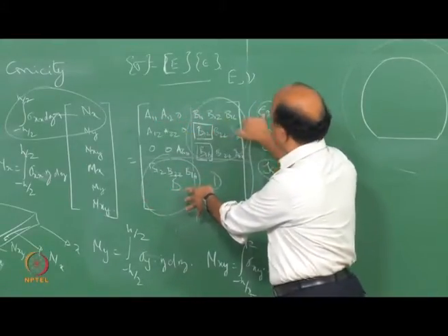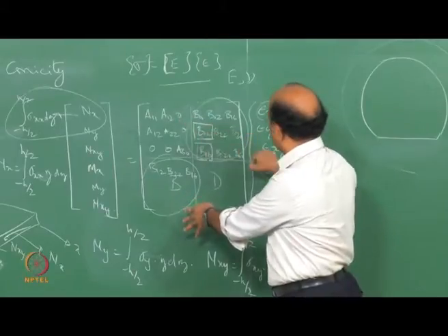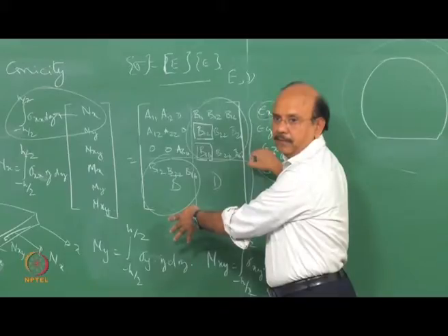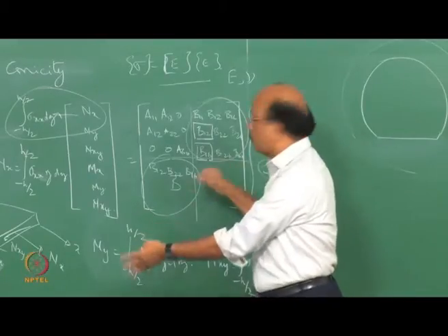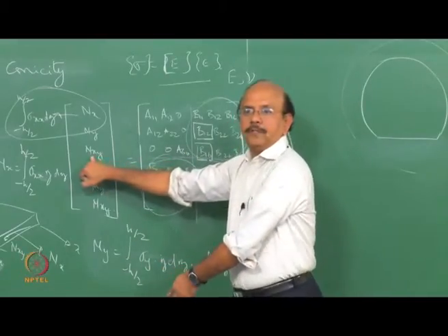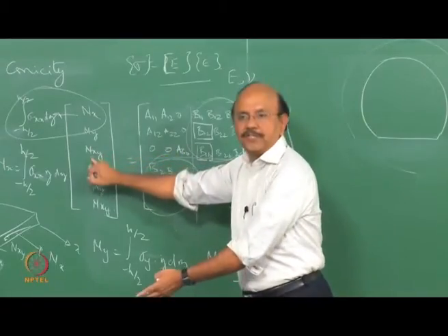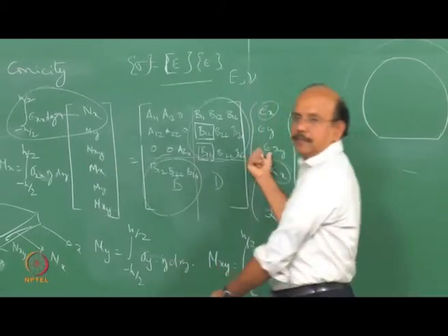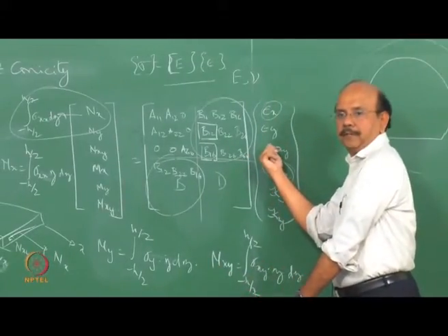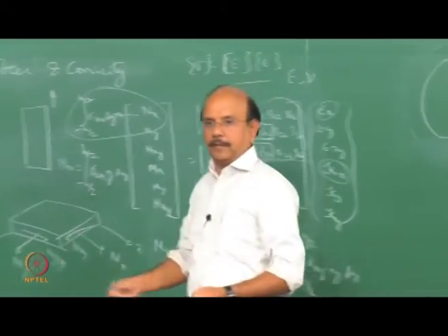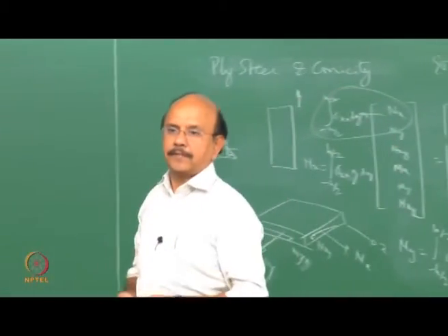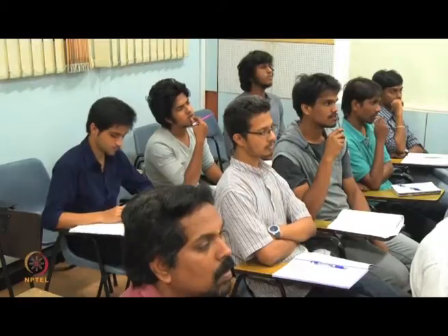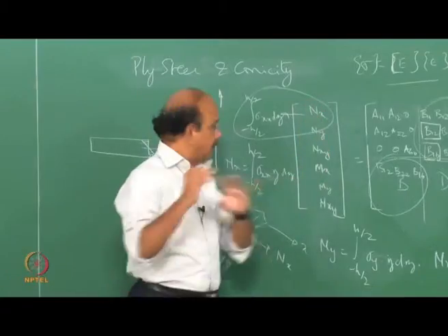Okay, A11 into epsilon x, A12 into epsilon y, 0 into epsilon xy or gamma xy, or however you call it. Okay, right? That's all. So the shear force, or the shear stress, which is the result here, is nothing but this multiplied by the shear strain. Right? Okay. Does that clarify your doubt that there is a shear term involved that has nothing to do with the normal force terms? Okay, let's come back.